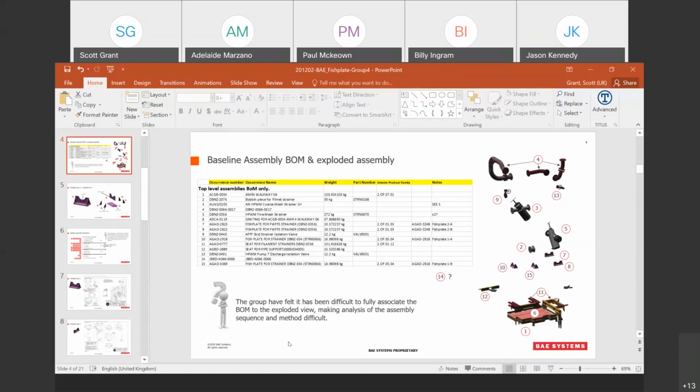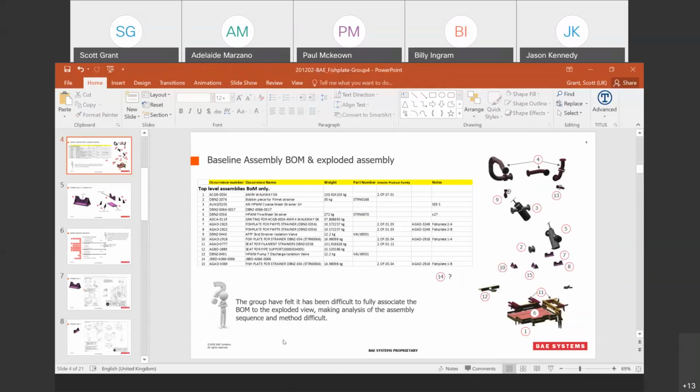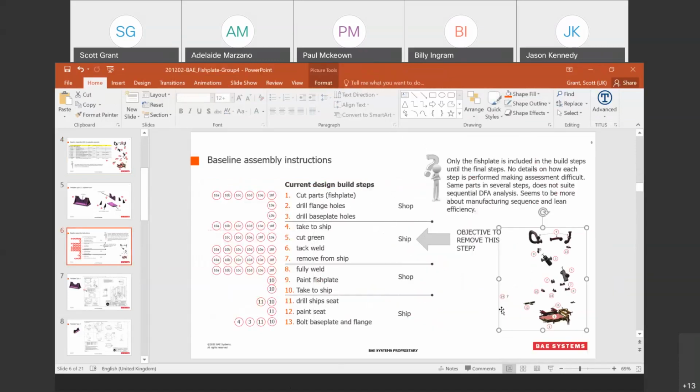And also you mentioned that the list of the bill of material, and then consequently the list of operation, are not correct, or they are not in the correct sequence. So all these things are important. That might lead to an inefficient assembly. One of the scopes of the DFMA is also starting from the bill of material. So if the bill of material is not correct, then as a consequence, the sequence of operation or the sequence of assembly related to the missing component might cause trouble.